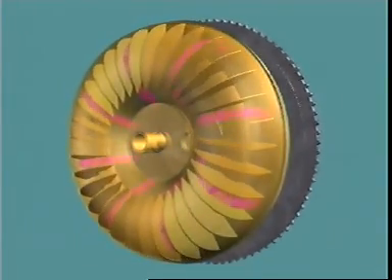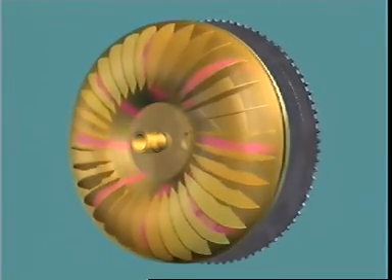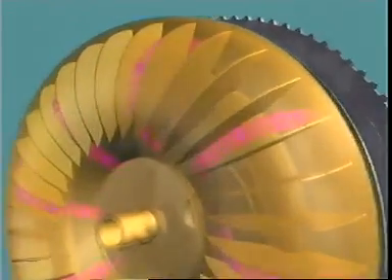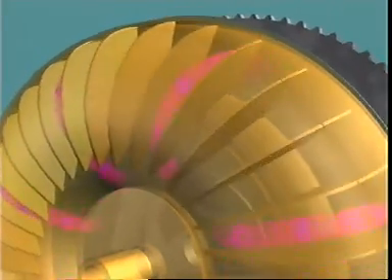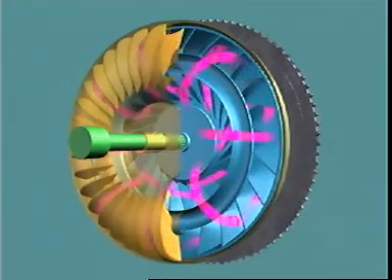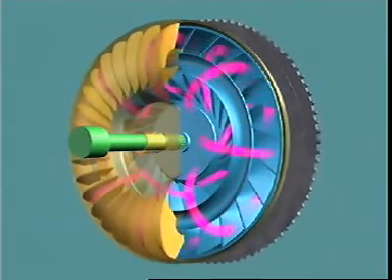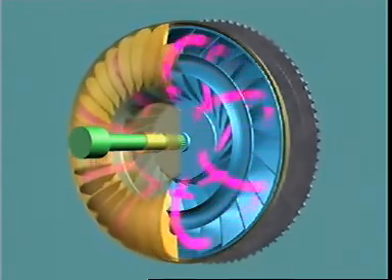Centrifugal force throws fluid between the impeller vanes outwards, around the back of the guide ring in a forward direction. This is due to the shape of the casing and the curvature of the vanes. With the engine idling and the vehicle stationary, little torque is transferred from impeller to turbine as the fluid flow is too gentle.